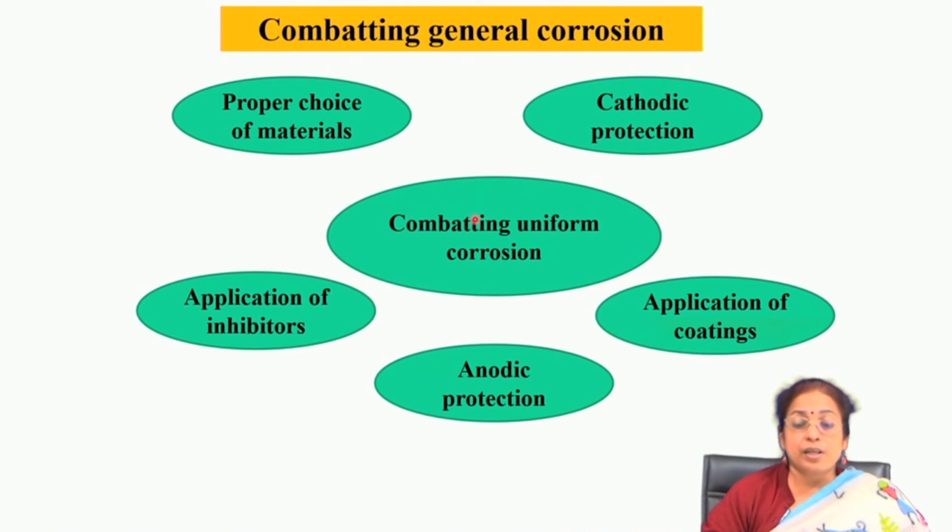You can as well apply a very thin coating made of a more active material, like zinc coating on steel. When zinc coating is applied on the steel, initially it acts as a barrier coating, and gradually, when the zinc gets corroded or damaged, it still protects the surface by the process of sacrificial action. So, you call it cathodic protection.